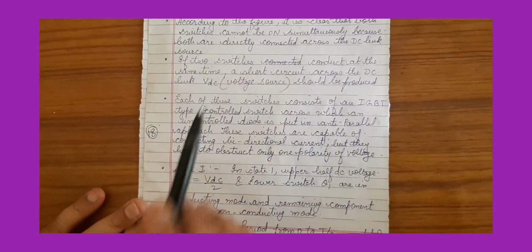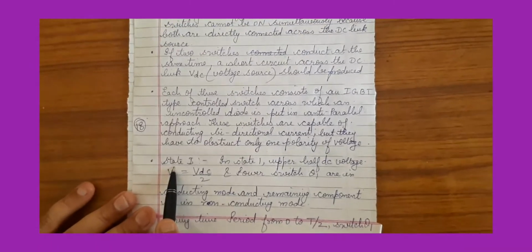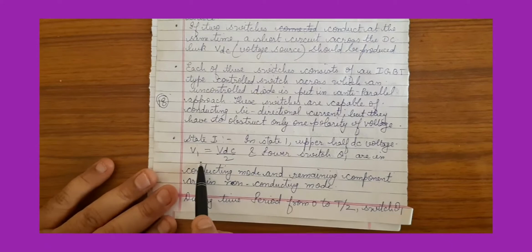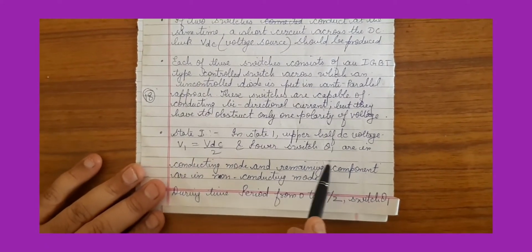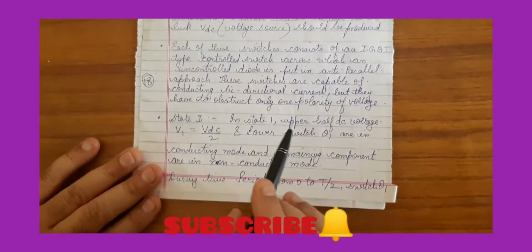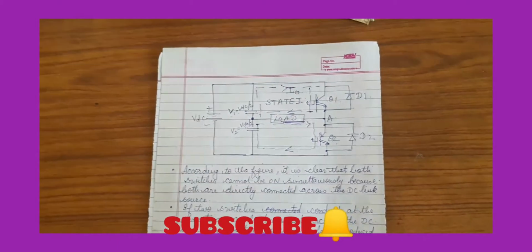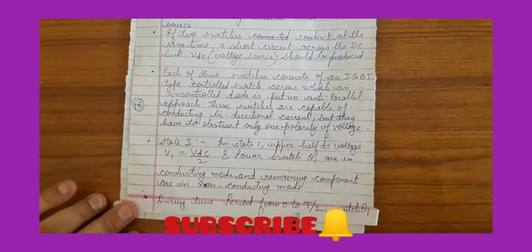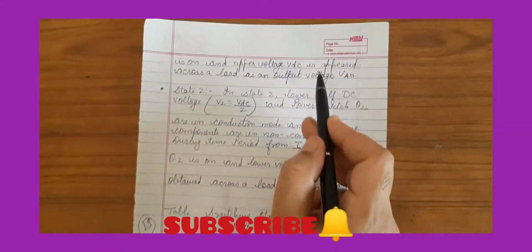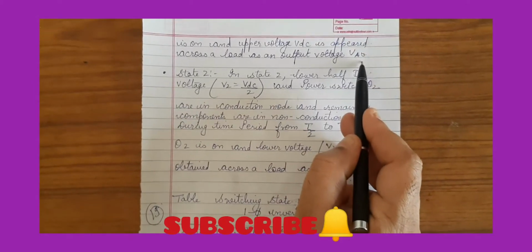Now the single phase half bridge VSI will operate in two stages. In stage 1, the upper half DC voltage, that is V1 equal to VDC upon 2, and power switch Q1 are in conducting mode and the remaining components are in non-conducting mode, and the current will flow like this in stage 1. During the time period from 0 to T/2, switch Q1 is on and the upper voltage VDC upon 2 appears across the load as the output voltage VAO.